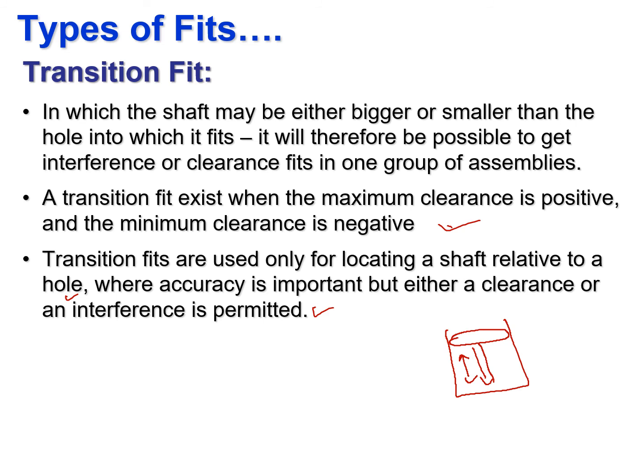In this direction, it actually pushes the exhaust out of the exhaust ports. Similarly, it sucks in the air-fuel mixture, but the air-fuel mixture does not go downward. The fit right here allows it to just remain above the piston in this region and does not seep into these regions.